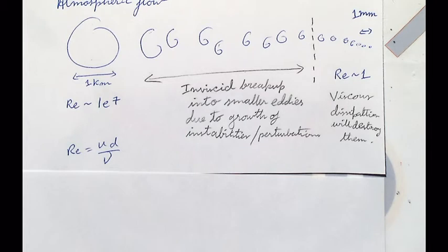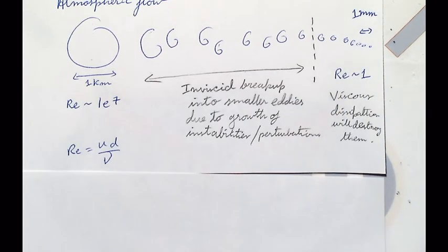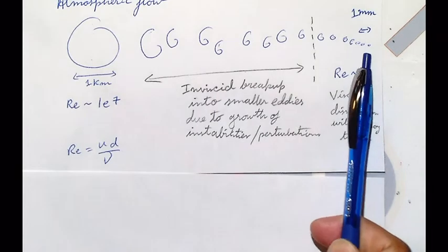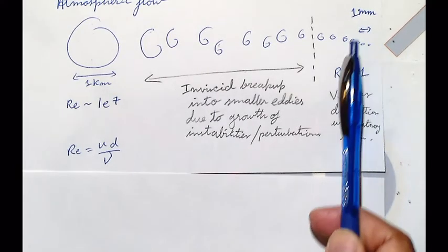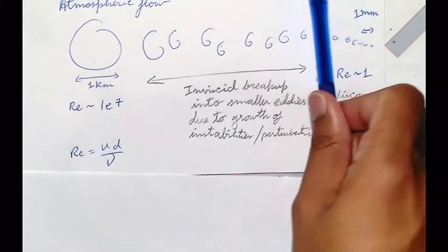Not clear? Okay, so think about your project, right? The project just said the velocity is cosine x times sine x, something, something. What's the first thing you do in MATLAB? Create a grid. Okay. When you create the grid, you have to pick grid size. How are these eddies related to the grid size? If they're too small, they can't be resolved. Yeah, if they are very small, you better pick your grid size to be small enough that you can capture these. If you cannot represent this on your grid, you're basically cutting all of them off.